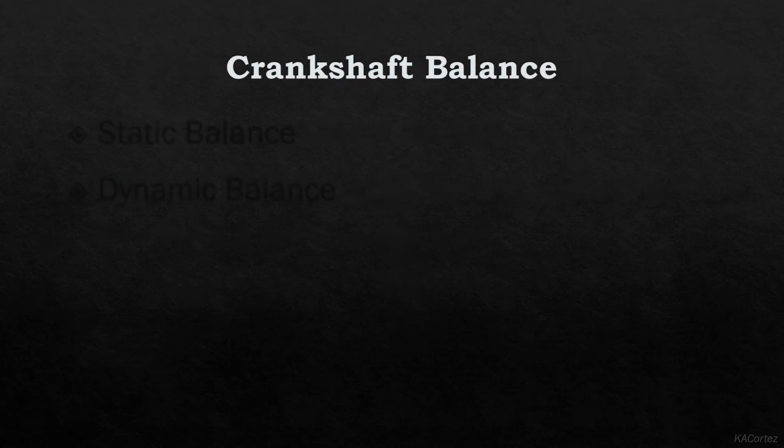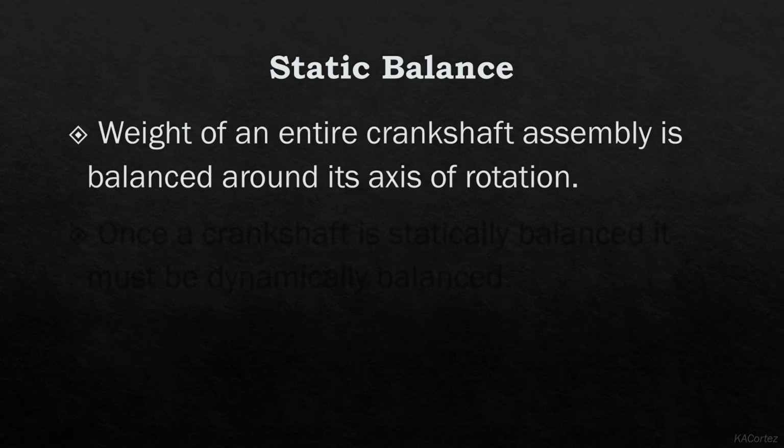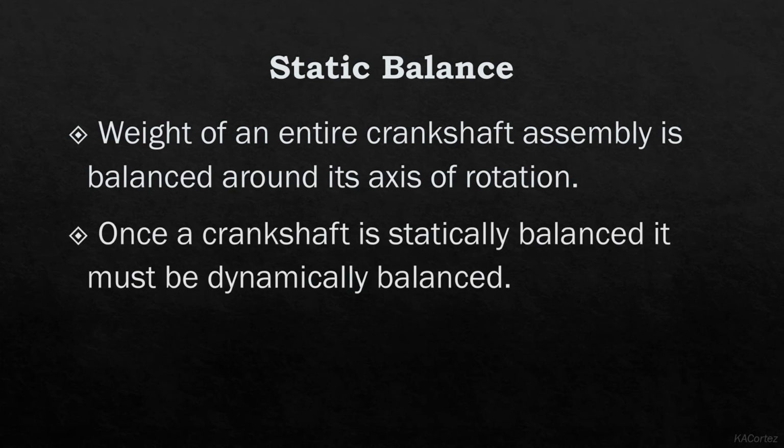The main purpose of the crankshaft is to transform the reciprocating motion of the pistons and connecting rods into rotary motion to turn a propeller. Therefore, it needs to be statically balanced and dynamically balanced. So what is static balance? This is when the weight of an entire crankshaft assembly is balanced around its axis of rotation. Once a crankshaft is statically balanced, it must be dynamically balanced as well.